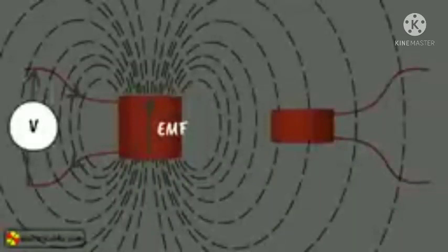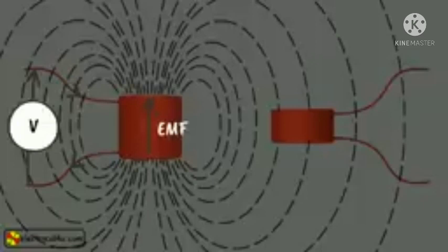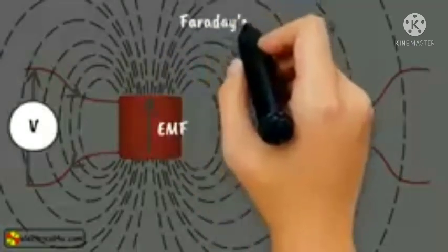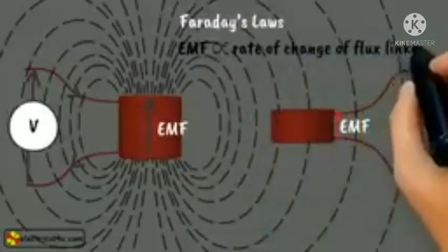We have said that there is another winding in the most basic transformer, but till now we have not discussed it. Now we are coming to the second winding. Supposing one separate winding is brought nearer to the first winding, then this second winding gets linked with a portion of varying flux of the first winding. Due to this varying flux linkage, there will also be an induced EMF across it. This induced EMF would be quite small, because the flux linkage is small. Hence, the rate of change of flux linkage is also small, and according to Faraday's laws, induced EMF across a coil is directly proportional to the rate of change of flux linkage.